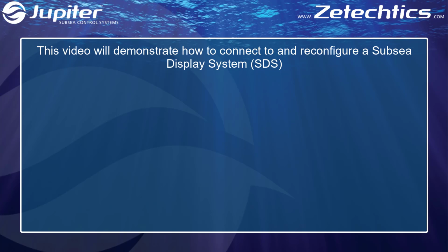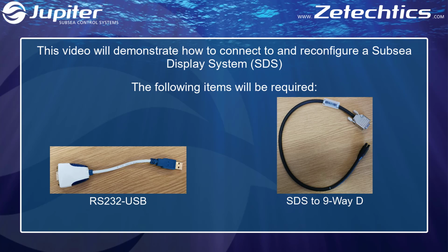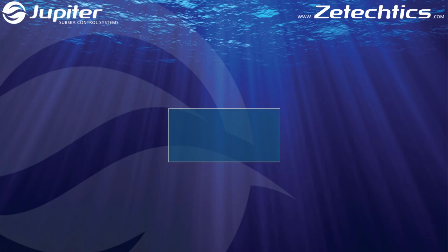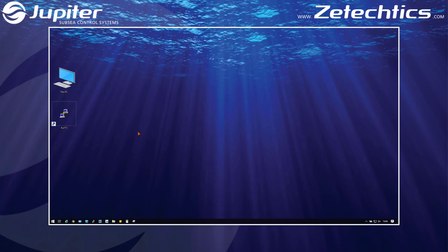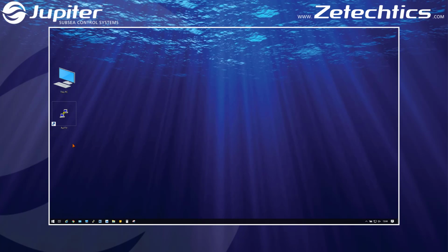This video will demonstrate how to connect to and reconfigure a Subsea display system. The following items will be required: an RS-232 to USB adapter and an STS to 9-way D cable. Ensure the RS-232 adapter is plugged in and installed correctly, then identify the assigned COM port.